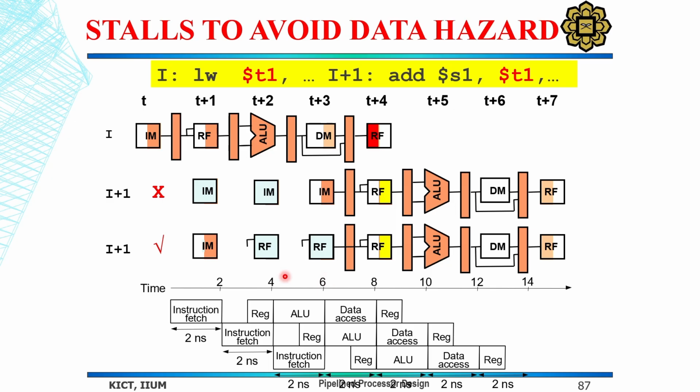So basically, what happens is that the stall puts in a delay which waits until the data is available. By adding the stalls, we add a delay, and during those cycles the program counter is not incremented. It just keeps on the previous instruction.